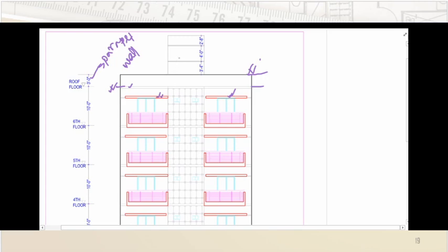Can you see there are two parallel lines and two sets of two parallel lines there? What does it indicate actually? From our visual inspection we can say, as this is 3 feet and this is 3 feet 4 inch, that means 6 feet 4 inch, which is probably the 7 feet door. It is indicating the door height up to which the door opening should be there in the roof.